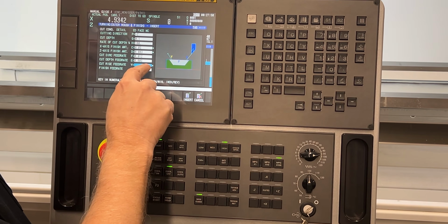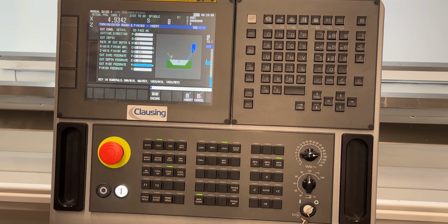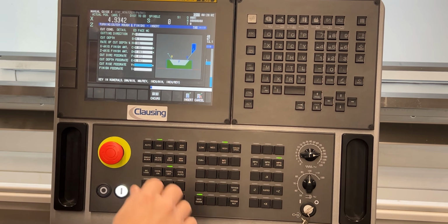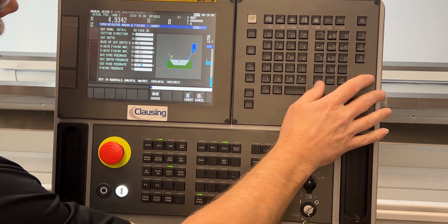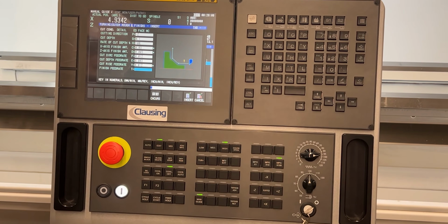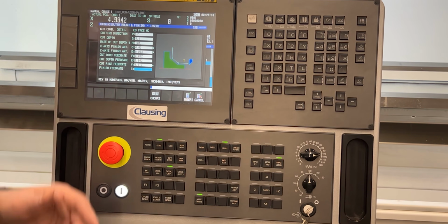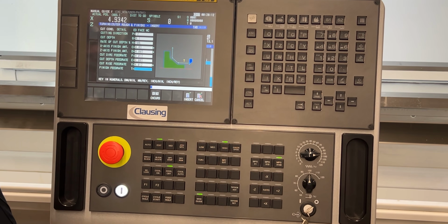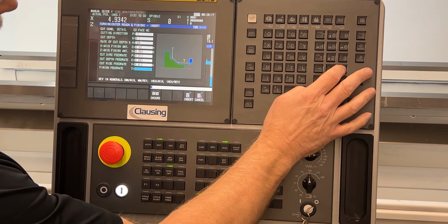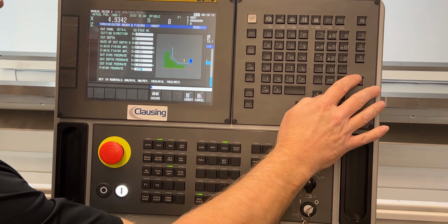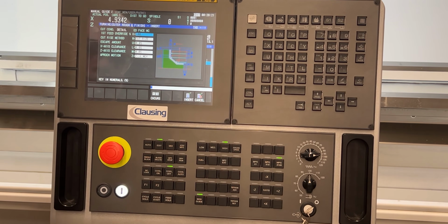And if I don't put a value in there, it'll revert back to the cut depth feed rate. But typically coming out, I want to speed it up. So let's go to 12 on that. And then my finish feed rate, what kind of feed rate do I want for that finish pass? I'm going to put that to, let's say, 5 thousandths per revolution.